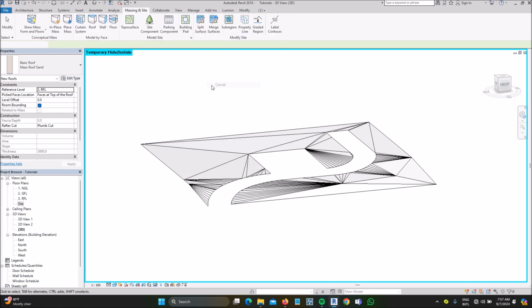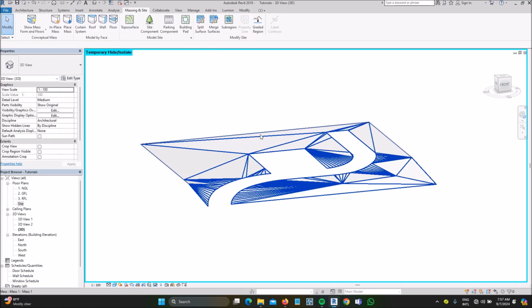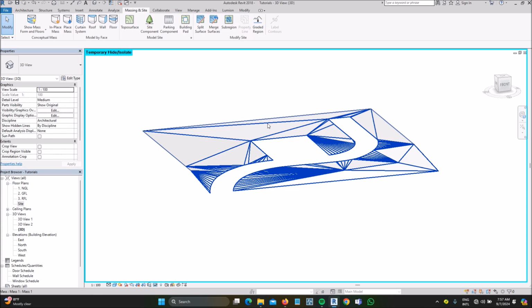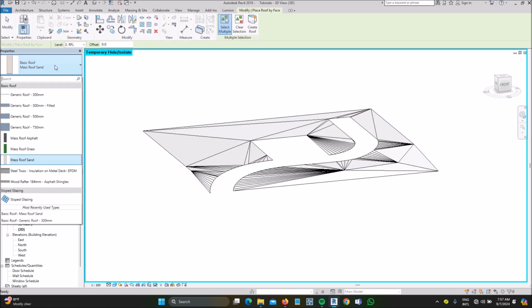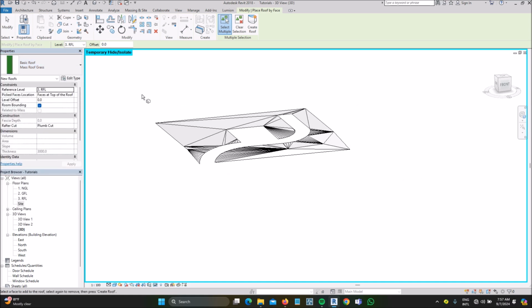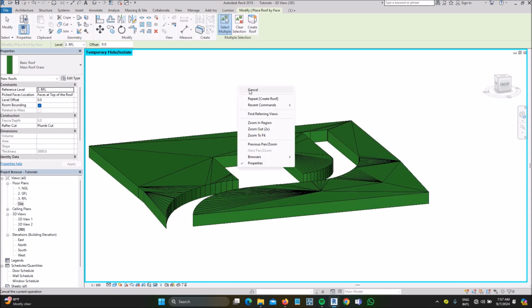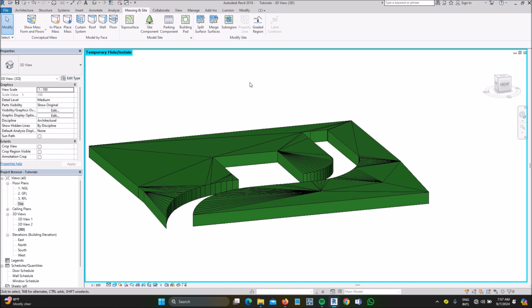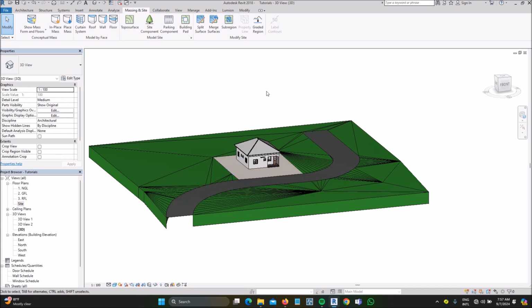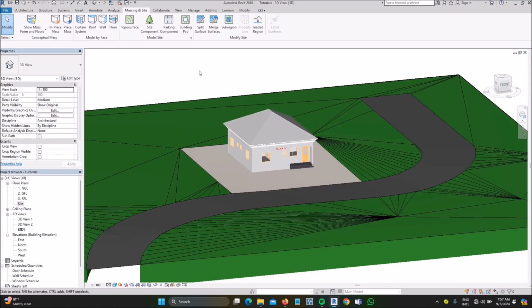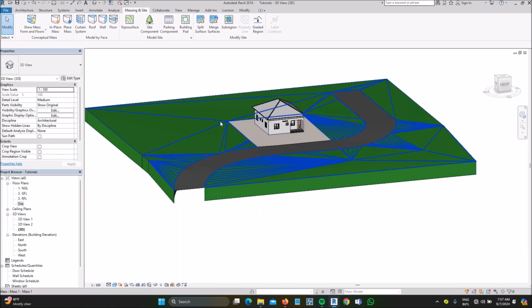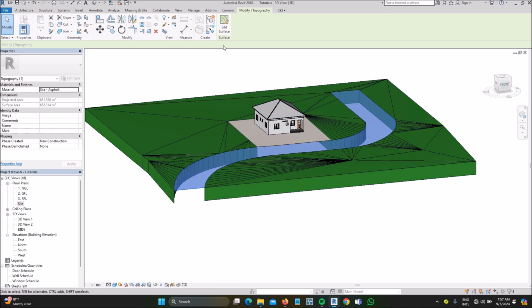So here on massing and site, importing, after creating the mass, so you go to roof, select the one you want. We are still on grass, so mass roof grass. You press Ctrl down, you highlight everything, then you create mass. So now you can build every other material there. So the same thing you do with this, the asphalt.